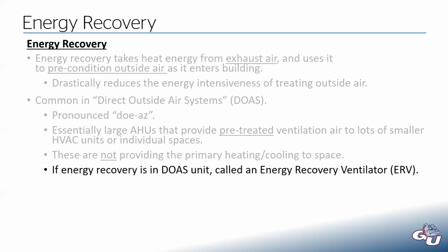If you have energy recovery in a DOAS unit, they usually call that an energy recovery ventilator, or ERV. But a DOAS system does not necessarily need to have energy recovery. It's just very commonly done. If you had a very small DOAS unit that was maybe a couple hundred CFM, that probably wouldn't warrant an energy recovery system on it.